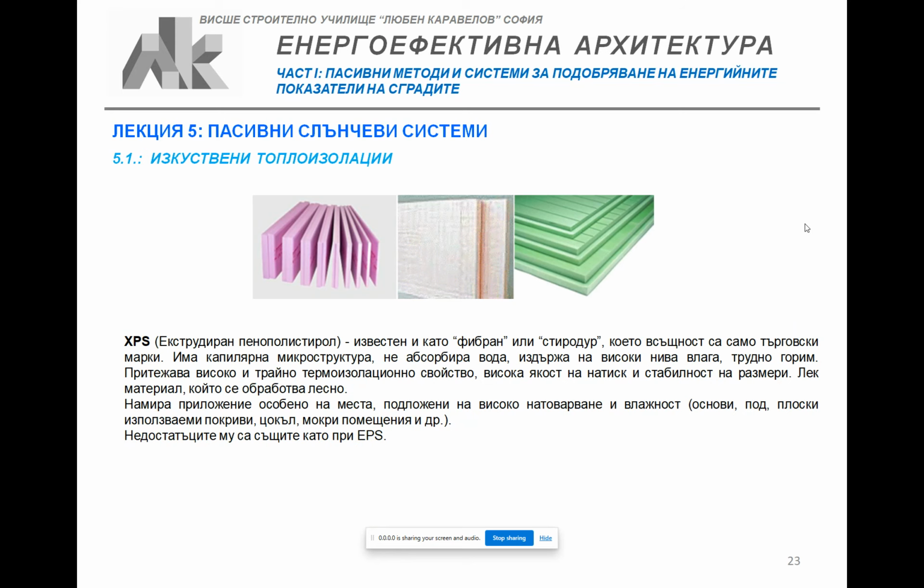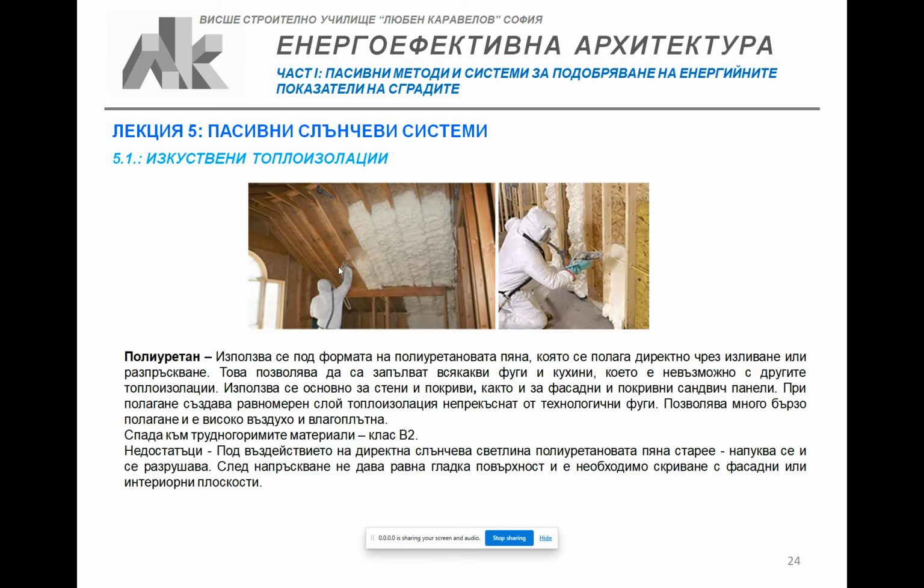Its technology is a little bit different. A certain mass of polystyrene is filled with small gas bubbles and then baked, and it extrudes and enlarges its thickness, and after that it's cut in the form it is needed, and thus it's much more stable and has higher insulation properties.